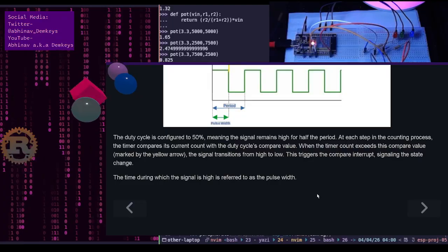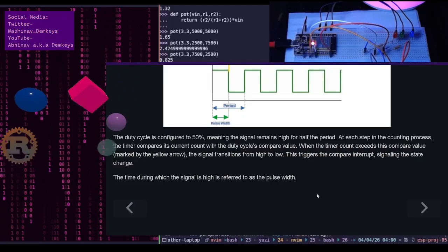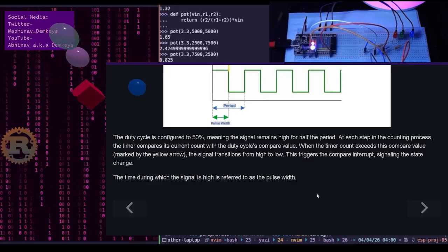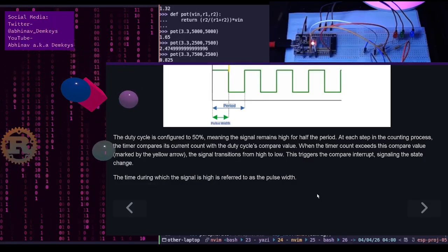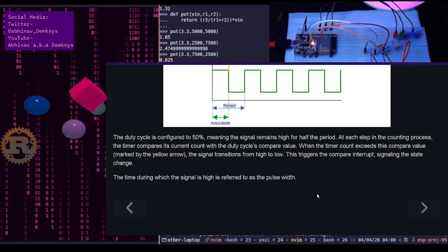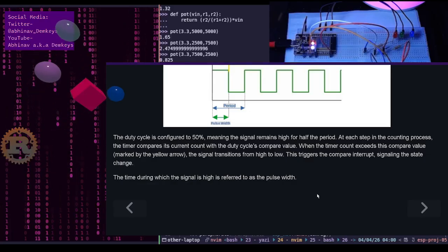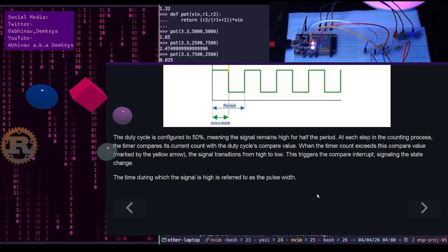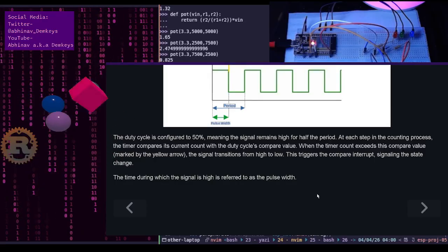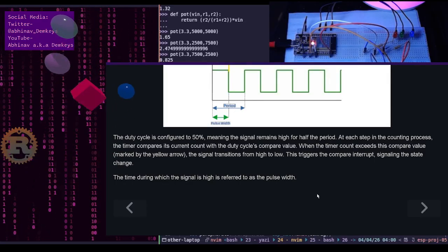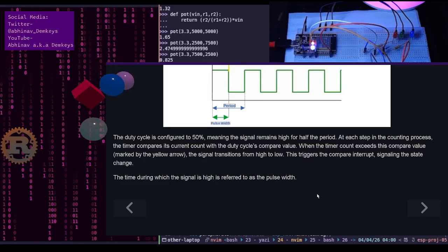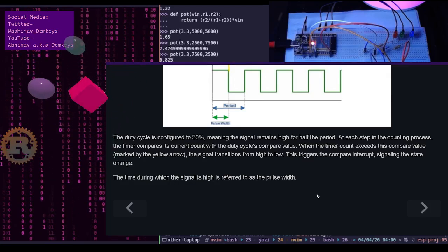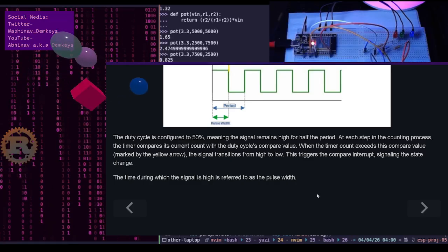And the units, it is measured in units of time, typically milliseconds or microseconds. Why it matters? For some components like servos, the duty cycle percentage doesn't matter as much as the specific pulse width. A servo usually needs a pulse width of exactly 1.5 milliseconds to stay at center, regardless of whether your frequency is 50 hertz or 100 hertz. I didn't know that.